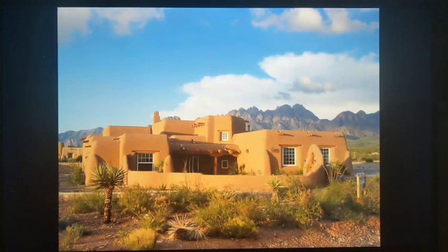But this is still a construction method that we see if you go to the Southwest today with adobe construction. The advantage in the desert is that when you have this massive temperature change from day to night, when the sun is out, the bricks are helping to insulate the home. So at night it'll get cooler, the bricks will get cooler, and then when the sun comes up, those bricks will keep the house cool. As the day goes on and the bricks heat up, when it gets cool at night, it will help to keep the house a little bit warmer than it is outside. So it really helps to control the temperature within those structures.